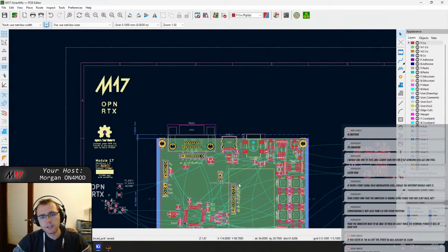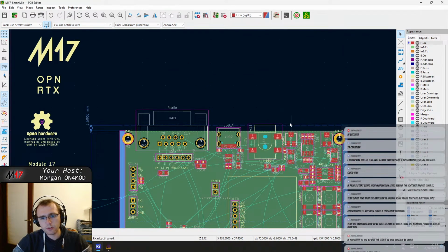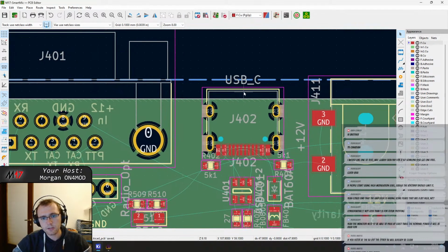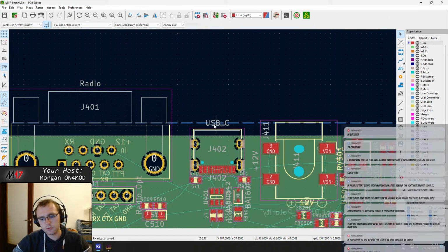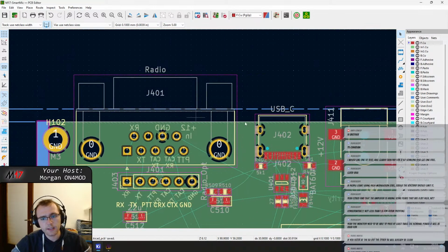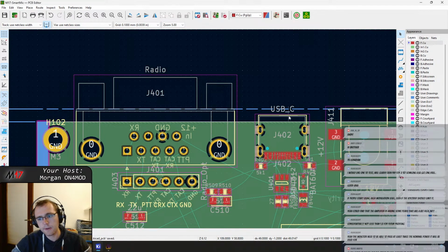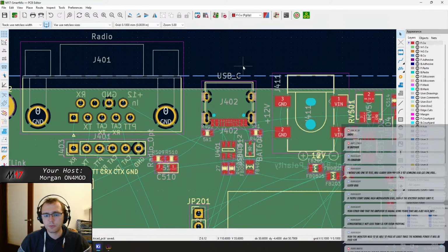So if I remember correctly, we had those protrude a bit from the face that might go on the side, but we have to pay attention that this one has to be as close as possible to the face that we are gonna add, so it has to protrude by at least 1.4, otherwise we might have troubles putting the cable in.